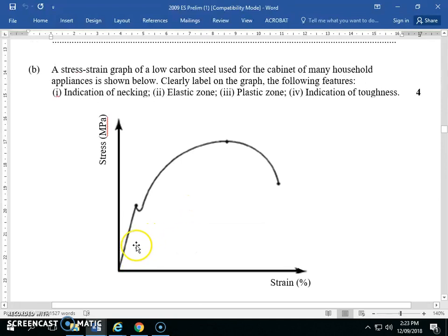Okay, so we have the plastic zone. The plastic zone is everything from that definite yield point, right? Everything past the definite yield point is the plastic zone. This is the elastic zone, this side here. Indication of toughness is the area under the curve, right? The higher it goes at any point, well, certainly the higher point in the elastic range is typically what we're interested in. This is the ultimate tensile strength, right? So the higher it is, the stronger it is. The longer it is, the more...